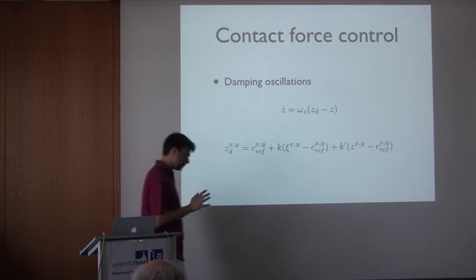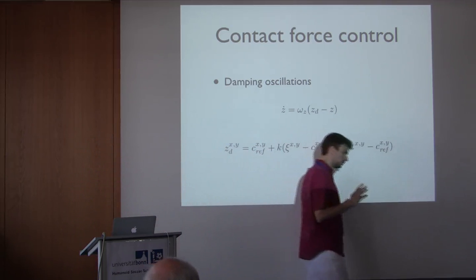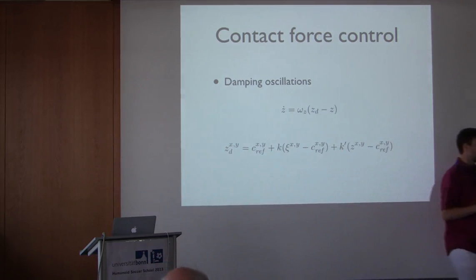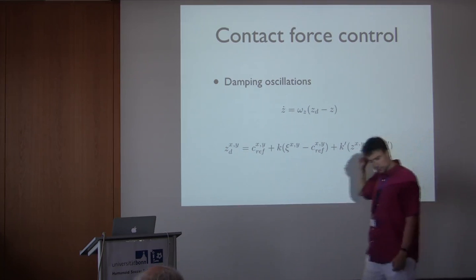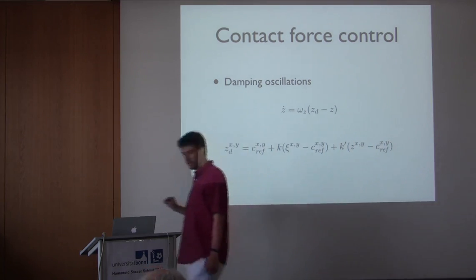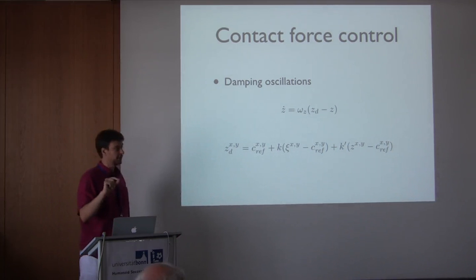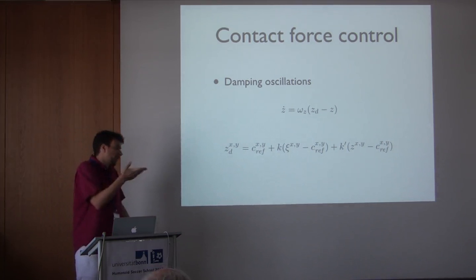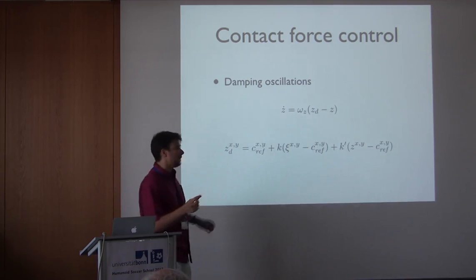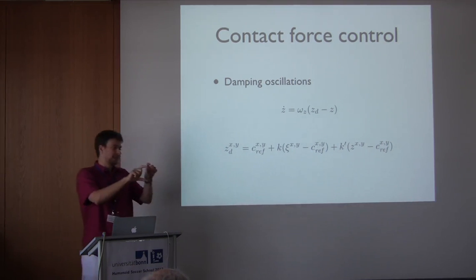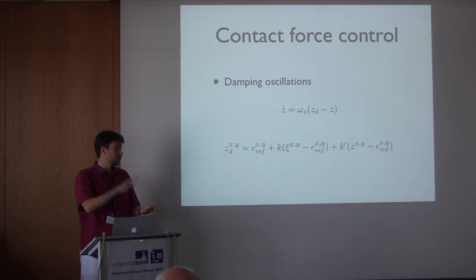So the main goal that you have usually for force control is damping. That's usually what people do. You can even see, if you look closely at videos of the Honda robots, or if you look at the videos of the HRP2 robot, or if you know how they are done, you know that they have elastic parts in the ankles so as to dampen those oscillations.